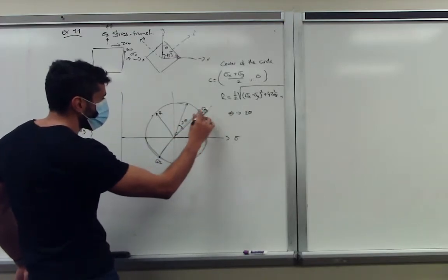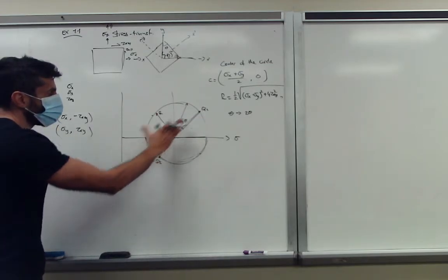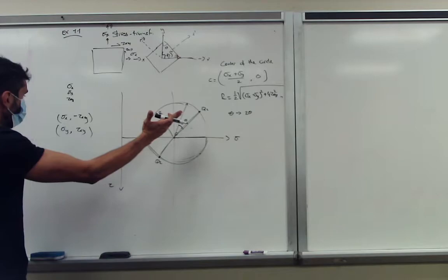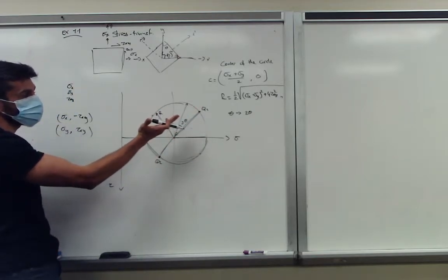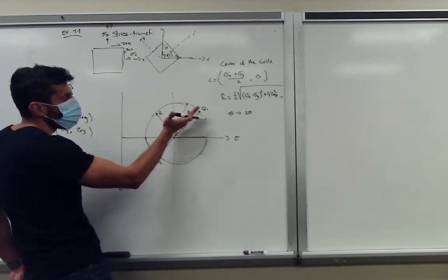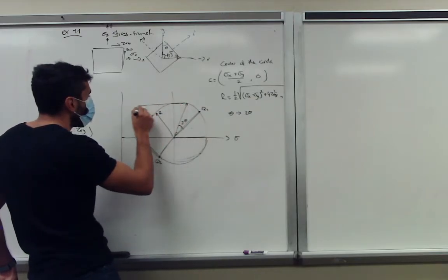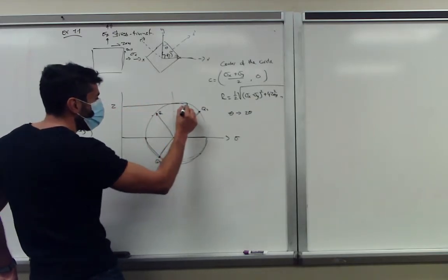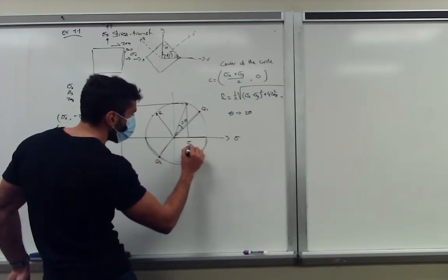So if you constructed your first points x and y, then for any rotation from the untransformed coordinate system by any angle theta, we can rotate on our graph by 2 theta, and we get our new tau and our new sigma out of it.